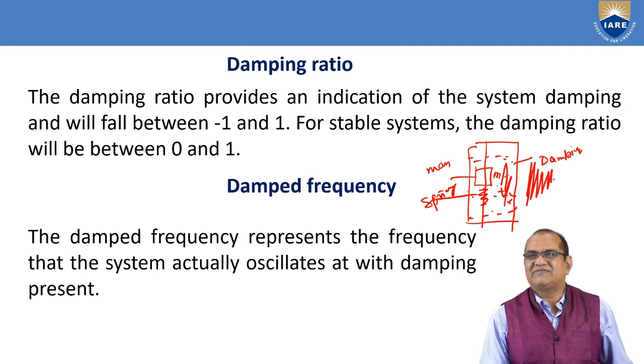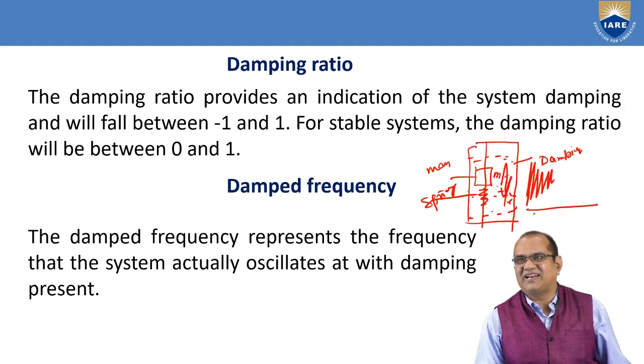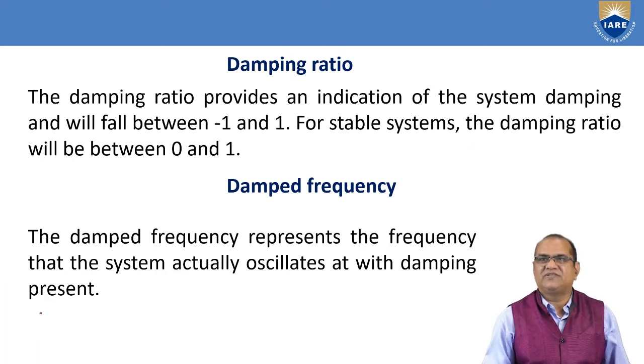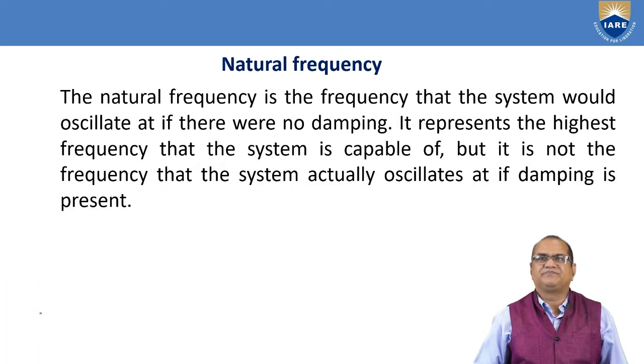But if dampers are there, slowly it will come down to the original position. That is the specialty of the damped frequency.